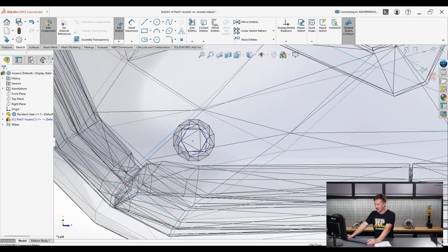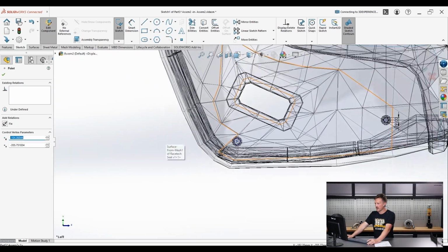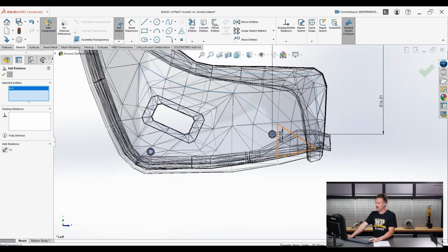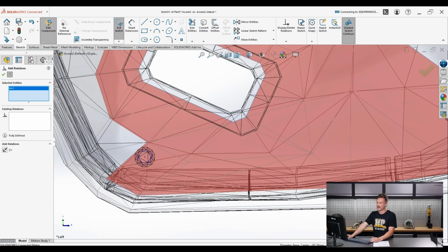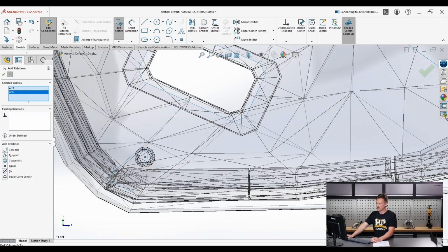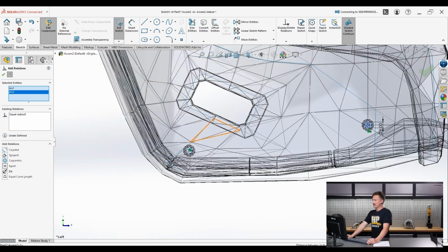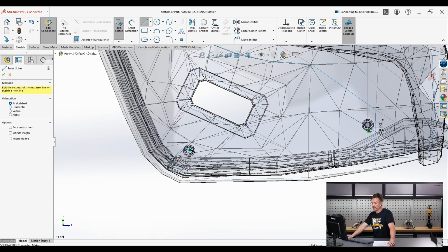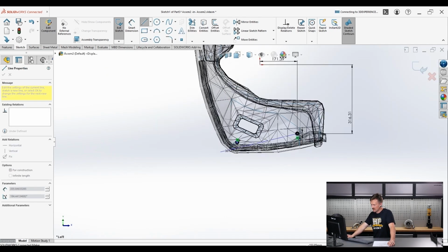And we'll just drag that roughly into the right position again, and we can add a relationship here between these two. So this is just like our constraints in Fusion 360. So we've got those two arcs, and we can just set them as equal so they're both of that equal 9mm diameter. And then I'm going to put another line in here, which may or may not be required, just between the center of those two.